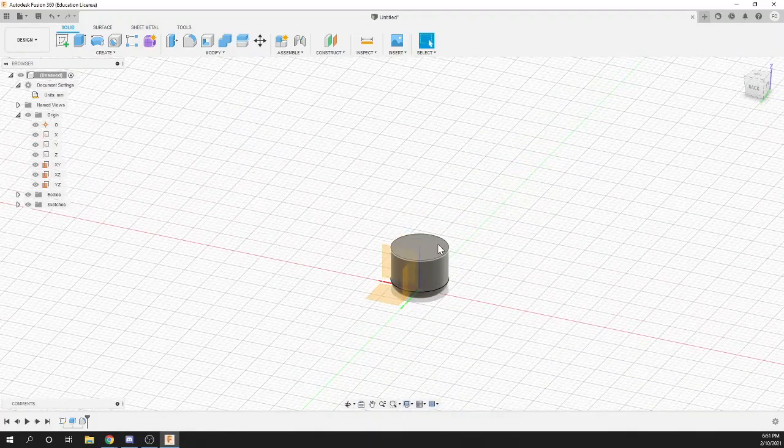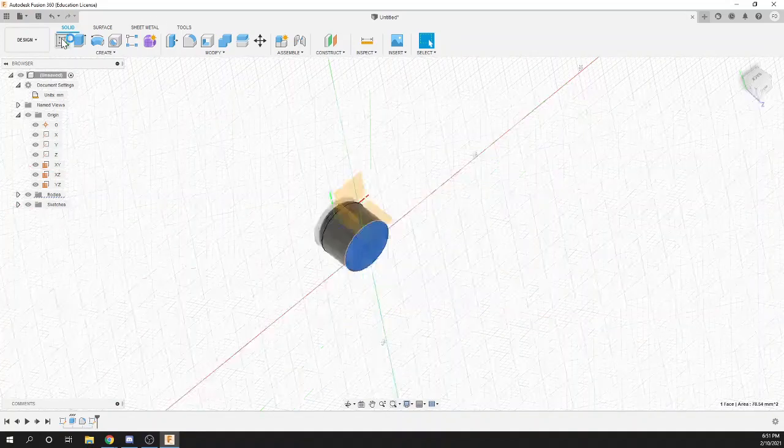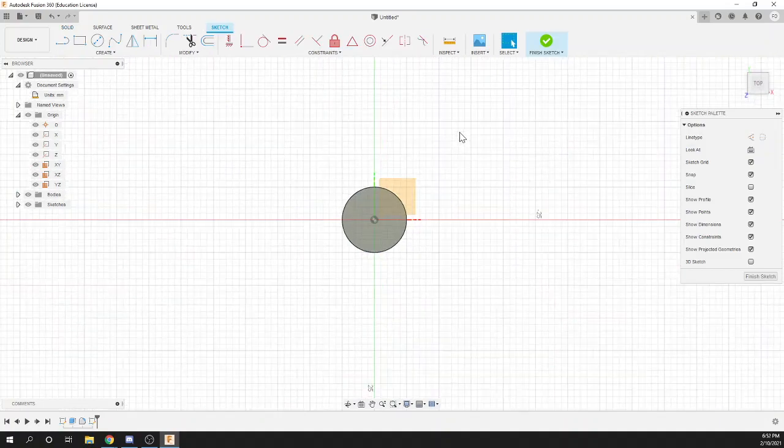The next thing we're going to want to do is, pencils have that little metal clip that connects the wooden part to the eraser, right? So next we can make that. What we're going to do is select the top face of our cylinder. It should be highlighted blue. Then we can create a sketch on that plane.